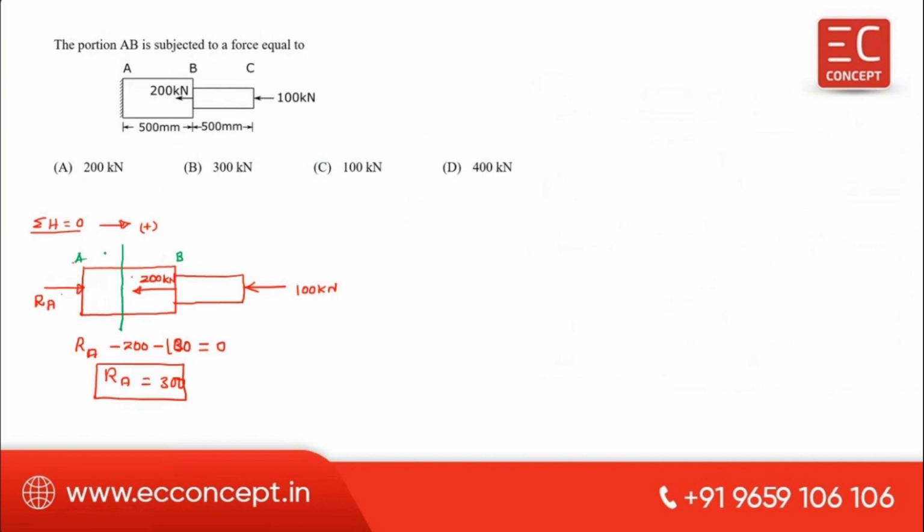If you take forces from the left, what is acting on this section is 300, right? Only RA is acting. From the right side, the net force acting at this section is 200 plus 100, which is equal to 300. Therefore, this section is subjected to 300 compression. So the answer for this question is 300.